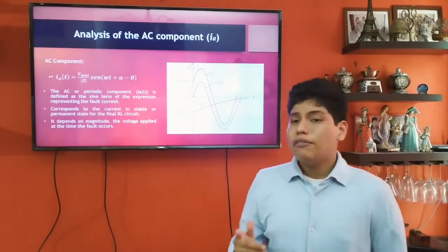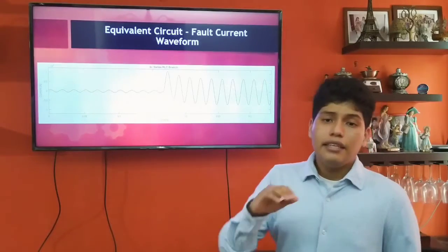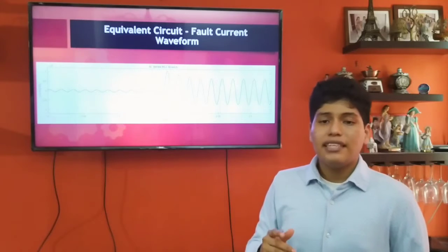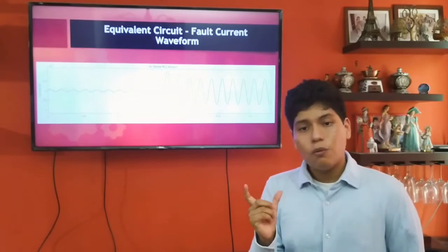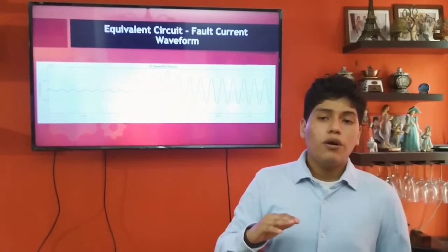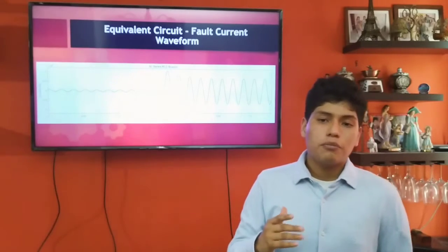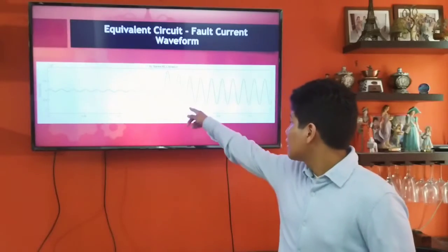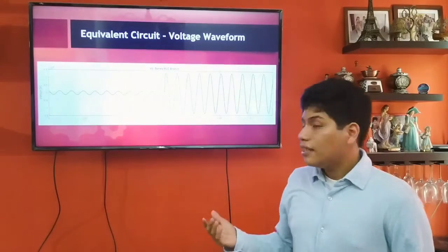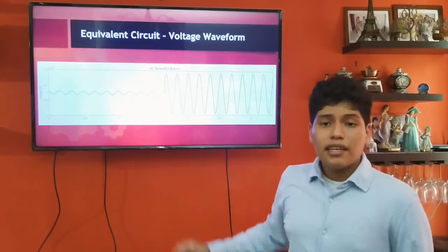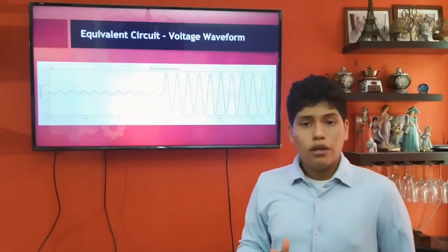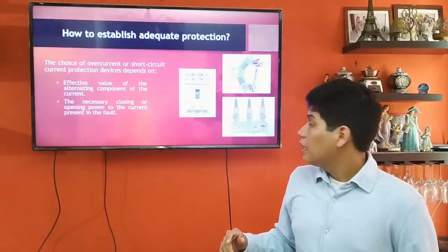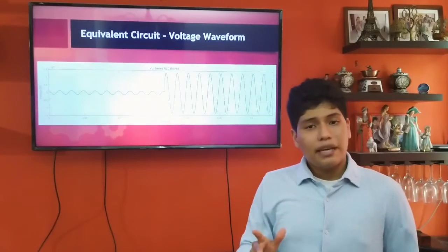Then the current graph versus time is as shown. If we remember the equivalent circuit proposed for this analysis, it presents an inductive passive component, which, as studied in this course, prevents an abrupt change of current. On the other hand, the voltage signal does not exhibit the same behavior, which generates a magnification of the current in a short period of time.